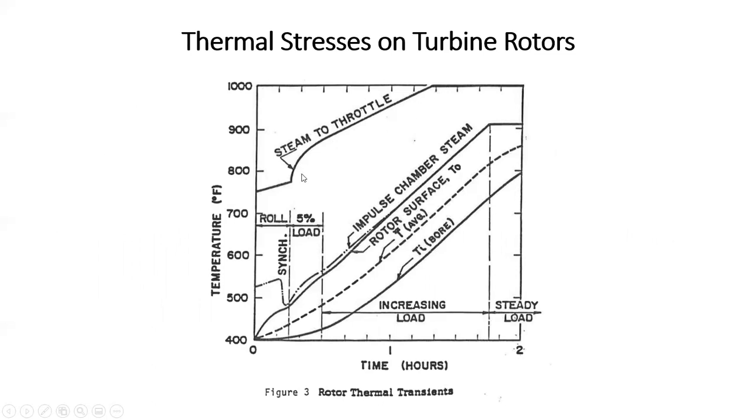We'll talk a bunch about this later, but this was a boiler characteristic primarily. And so when you get up to higher steam loads, the boiler can produce the 1,000-degree steam that we're basically designed for, but at low flows, not so much. So this is starting out showing about 750. It's going to depend on the particular boiler, but it's going to be much less than when we get up here, at maybe 60% load or something like that. We finally hit our desired steam temperature back here.